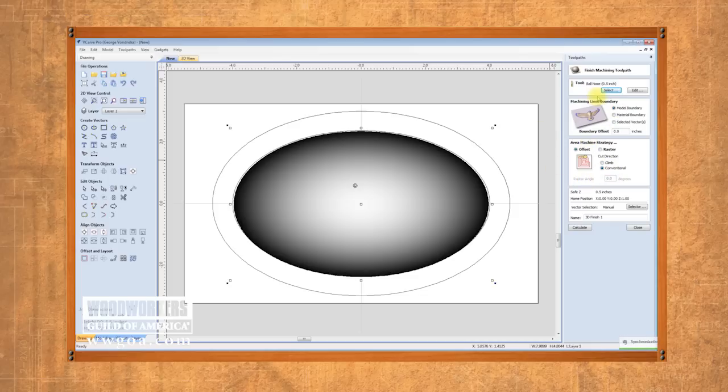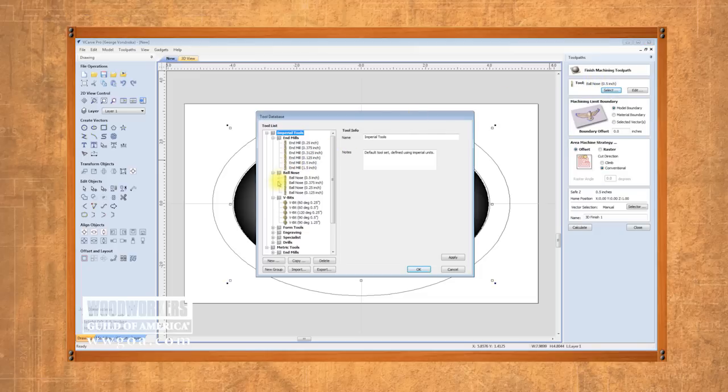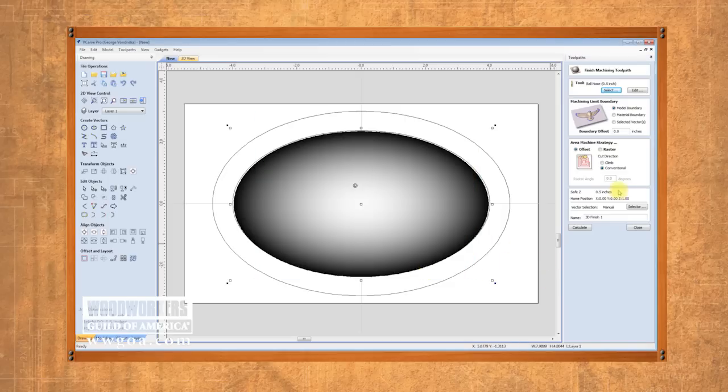What we need to do here is check our cutter. Now in this case, generally for this 3D finishing, you're not going to use a bit that's straight on the bottom. You want to use one that's round on the bottom. That's all of our ball nose cutters here. And again, pick the size of the cutter depending on the size of the work you're doing. So we're going to go with a 1/2 inch, a 0.5. And I'm going to change my title, 0.5 finish.